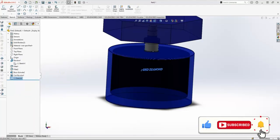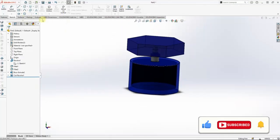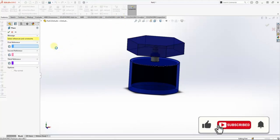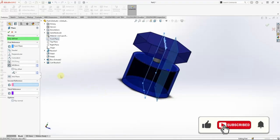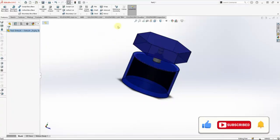So let's just click delete. Say yes. Let's click delete. Say yes. Now come right here to features. Come right here to reference geometry. Let's click it. Let's make a plane. The reference geometry is going to be the front plane at a distance of, let's see, let's just draw this out. Oh, sorry. Should have been 1. Sorry. That was a mistake on my hand.